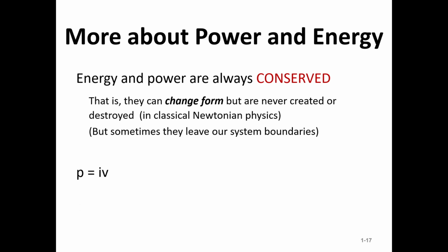Okay, these are our power formulas. P equals IV, so power equals voltage times current. And if you take Ohm's law and solve it a couple of different ways and then plug it back into P equals IV, you get 2 more formulas that are useful. You get I squared R and V squared over R.